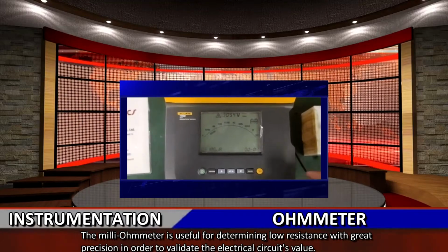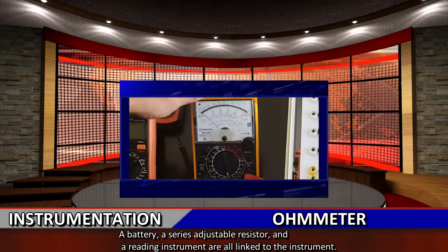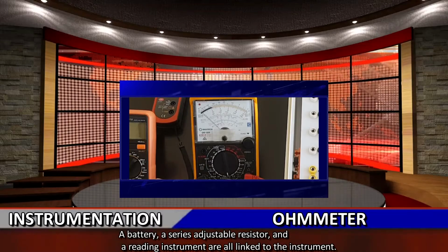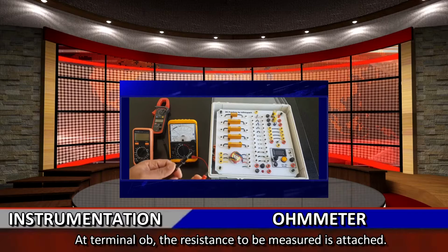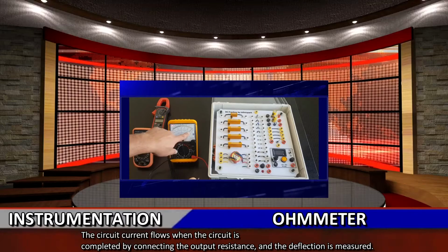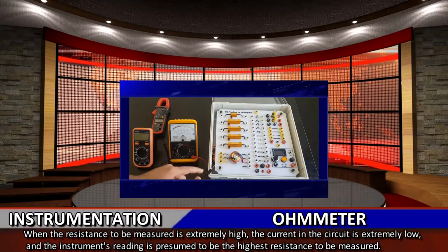So, the working principle of an ohmmeter: a battery, a series adjustable resistor, and a reading instrument are all linked to the instrument, and at terminals OB, the resistance to be measured is connected. The circuit current flows when the circuit is completed by connecting the unknown resistance, and the deflection is measured.